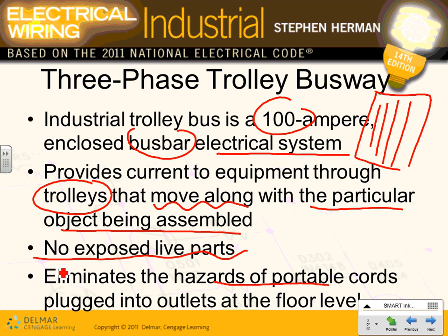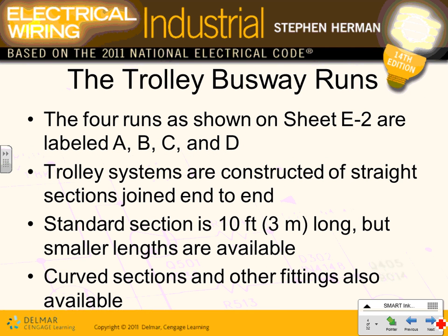And in order to work on this piece of equipment, you have two options. Either you have trolley busway that you can move it along a predetermined track, or you can plug and unplug the equipment as you move through the long assembly line. So you can imagine every time you plug and unplug, what happened? These are three-phase plugs. You expose yourself to more hazard, electrocution hazard, arc hazard, damage of the equipment, and so forth. So plugged into the outlet from lower level, it's safer, more unique. Keep the equipment above, keep all the tools above you.